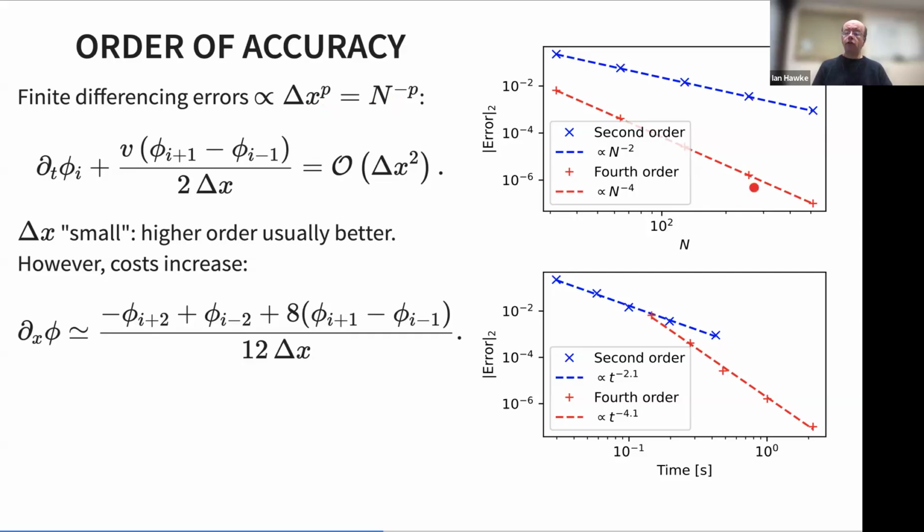So you'll see plots like the one in the top right, where the logarithm of the error scales with the logarithm of the points, and the slope gives you the order of accuracy of the method. We can see that for a given error, the number of degrees of freedom needed for the higher order scheme is much, much lower. Therefore, these methods appear to be more efficient.